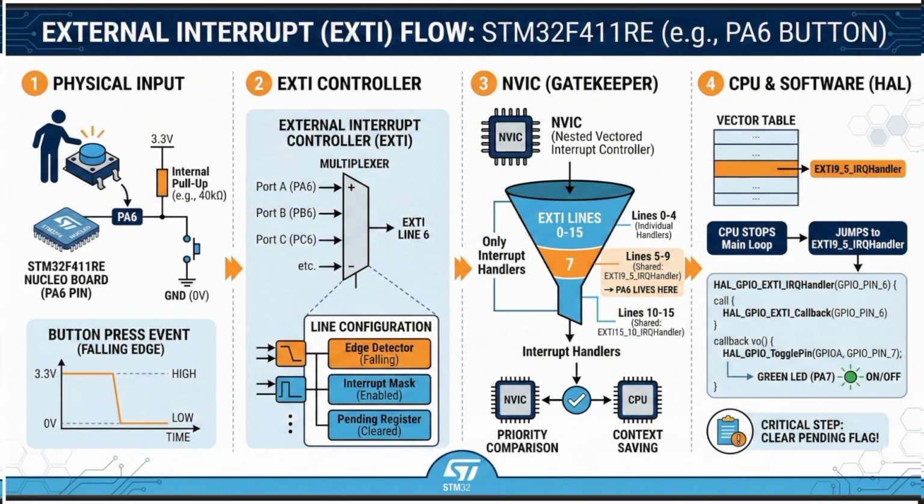If the pin is floating, it will act as a small antenna, and as a result it will collect some random electrical noise in the form of EMI. Our CPU will interpret this as a random sequence of zeros and ones. To avoid that, we need to set the pin to a known state that can either be logic high or logic low. Here we are using logic high, so the idle state is going to be 3.3 volts. Once the user presses the button, it is going to connect to ground, and that is going to lead to what we call the falling edge. So the voltage here will drop to zero.